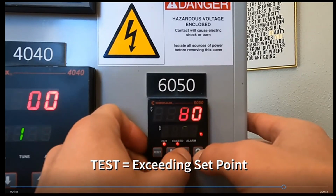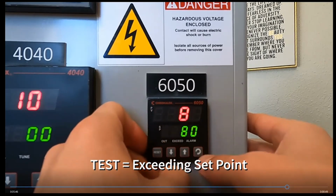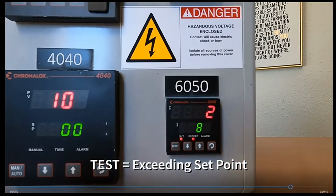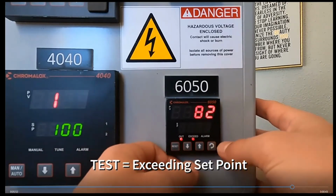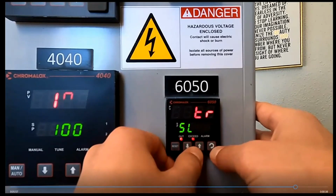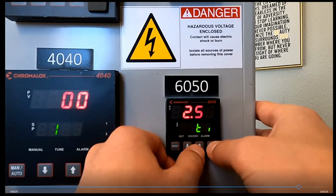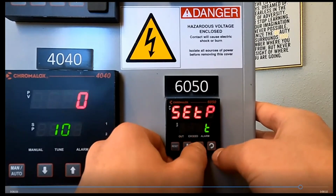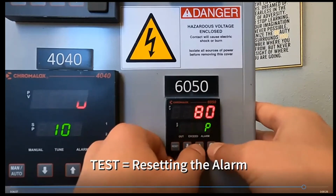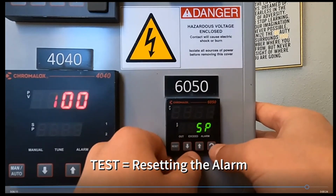Okay, so I dropped the set point down to below the actual process variable that was being read. The process variable is 82 Fahrenheit, set point is 80. So boom, the exceed condition happens, okay? And this shuts everything down. The exceed condition will go away as soon as the process variable is below your set point, which you'll see here in 1 second. So we're going to raise that. The exceed condition goes away.